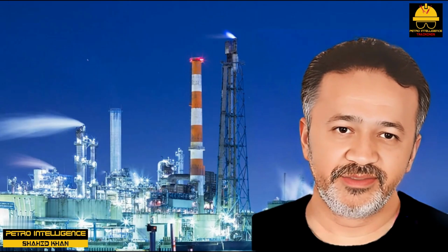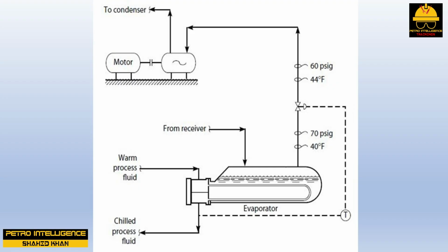Compressor operation. Let's say we have a centrifugal refrigeration compressor driven by a motor. The motor is tripping off because of high amperage. Should we open or close the suction throttle valve shown in the picture? Answer is close it. Of course, both the evaporator vapor outlet temperature and the process fluid outlet temperature will increase. But that is the price we pay for having too small a motor driver on the compressor.